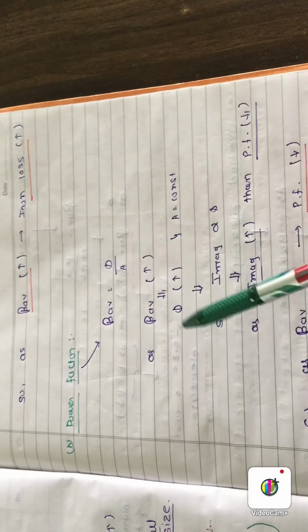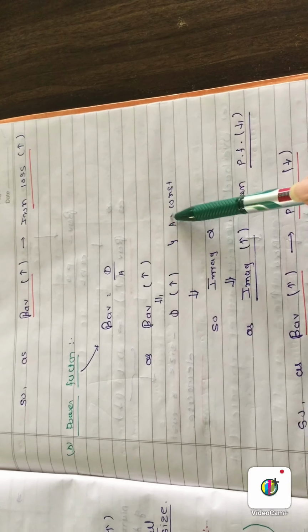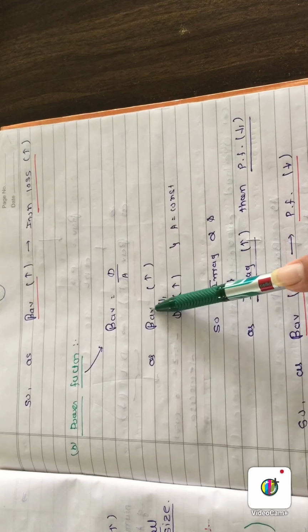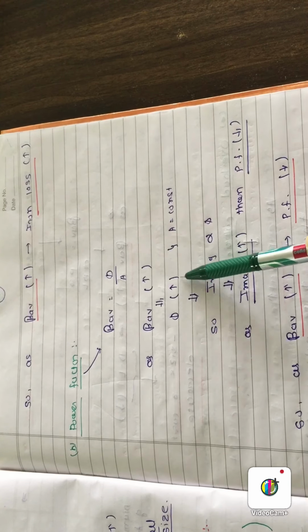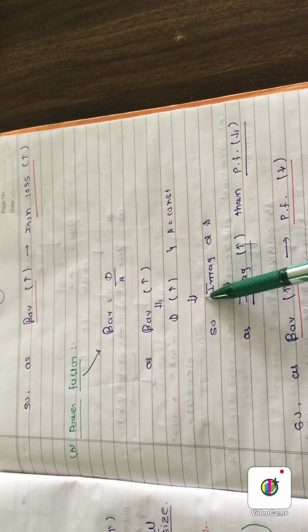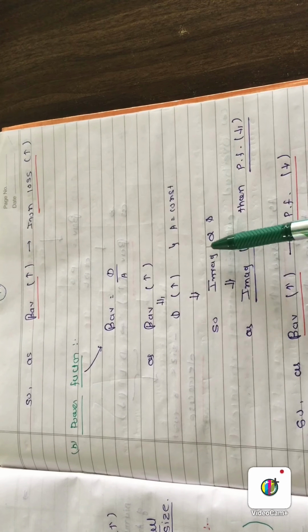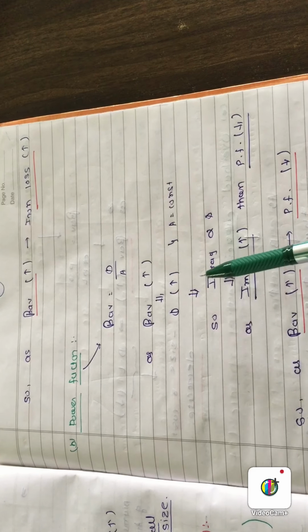Okay, with increment in BAV, phi will also increase if you are keeping A constant. So I can say that with increment in specific magnetic loading, the flux will also increase. Now with increment in flux, magnetizing current will also increase. Why? Because magnetizing current is directly proportional to phi, and phi is due to the magnetizing current.